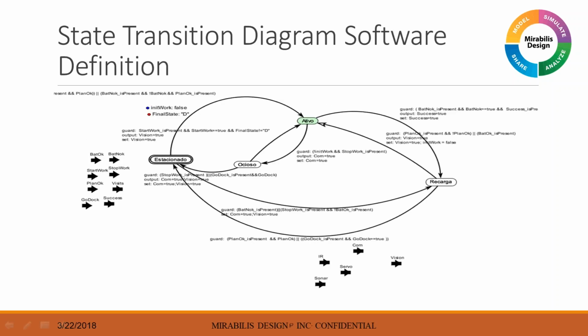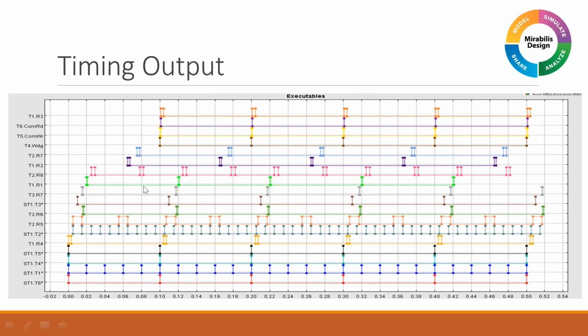So what you can do is create state transition diagrams of this kind, and then run the simulation of these and look at the effective power consumed, or the effective response time, or the buffering, or the usage of different tasks and things like that. Here, what it's showing you is, for all these different tasks, what time they actually executed.